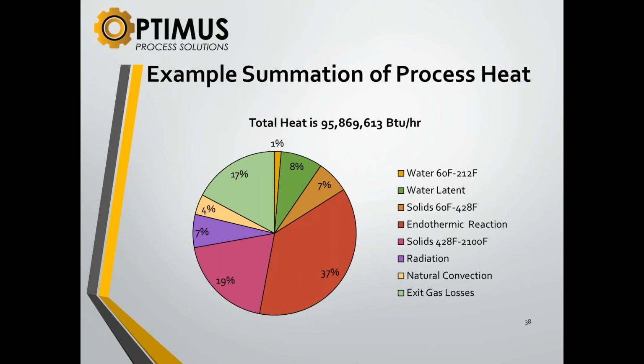If you have carbon monoxide, carbon dioxide, O2, if there's too much O2, you may be wasting a lot of heat or a lot of fuel, and this is more related to the kiln. And from this you can figure out your process capabilities, like the quality of the product. If your product's not doing as well, then this may be a way to look at the symptoms.